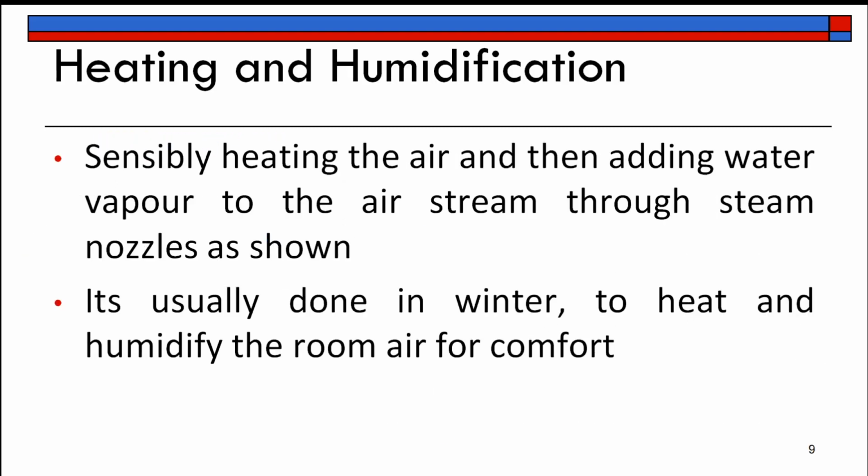Now the next psychrometric process is heating and humidification. So obviously you know that the temperature should be increased in cold countries and water content to be added, especially in a dry climate. So sensibly heating the air as well as adding water vapor to the airstream through steam nozzles. I'll show you the diagram. So it is usually done in winter.